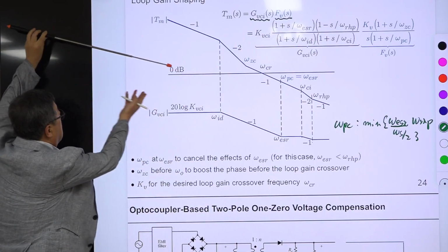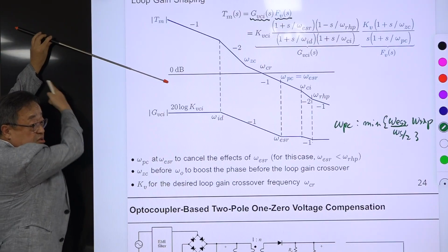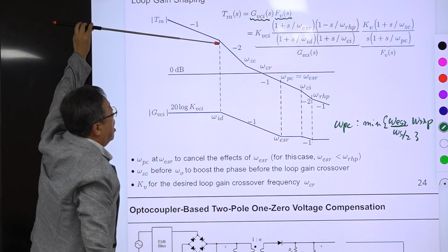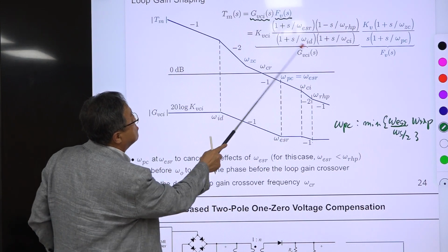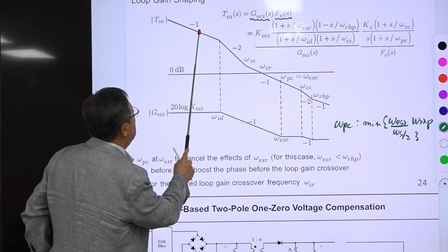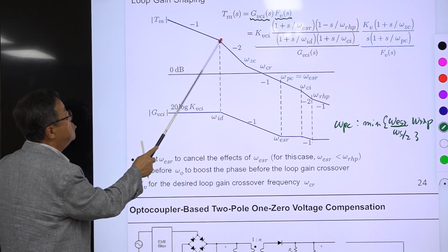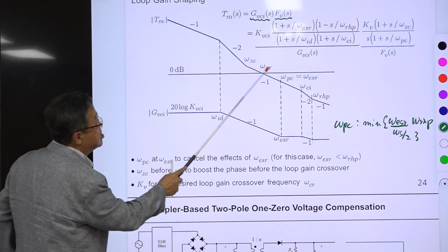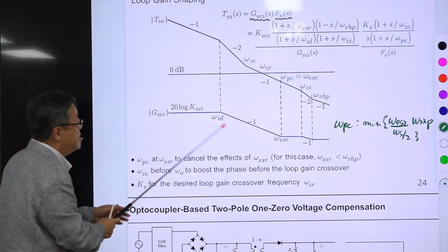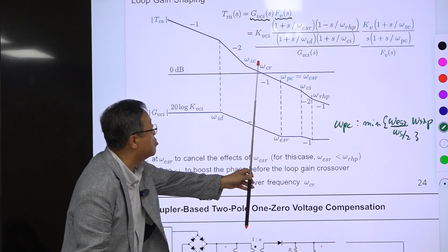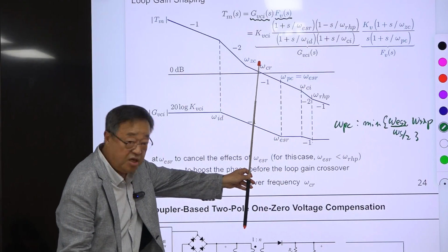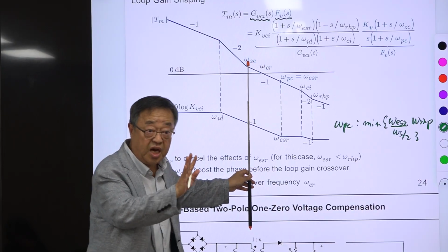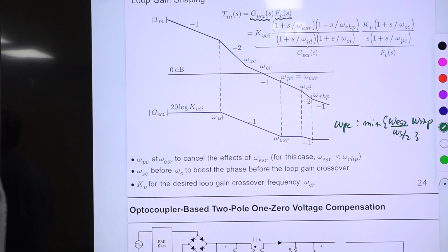It is declining with this slope from the 0 frequency. We cannot locate 0 here, okay, somewhere there, and it's coming down. Then at this frequency, we have this pole. So slope is changed from -1 to -2, and we have omega GC placed before the omega CR, which is loop gain crossover frequency. Here, it's different from omega CI. This is appearing first here, this omega CR.